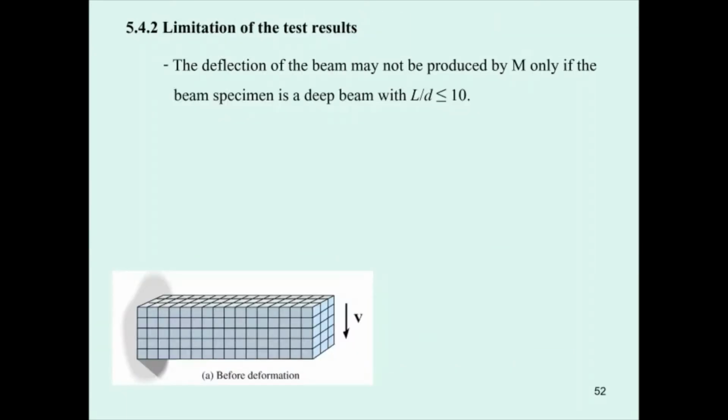Okay, there are some limitations of the test results of static flexural tests. First, the deflection of the beam may not be produced by the moment only. If the beam is a deep beam. What is a deep beam? It has the ratio of L over D less than 10. That means the beam has a shape like this.